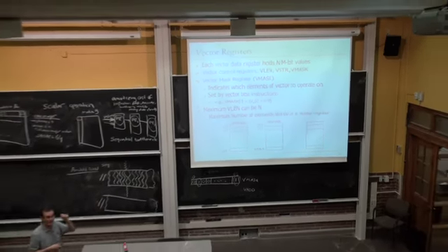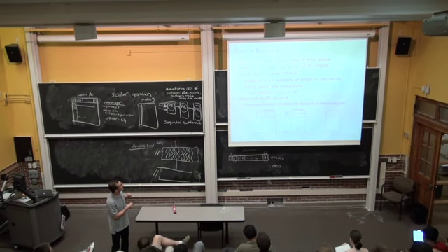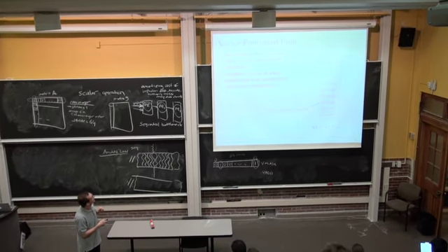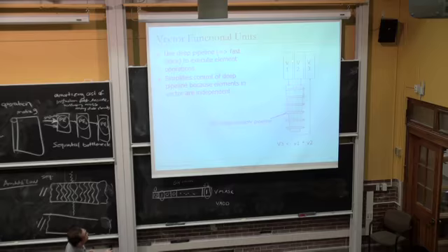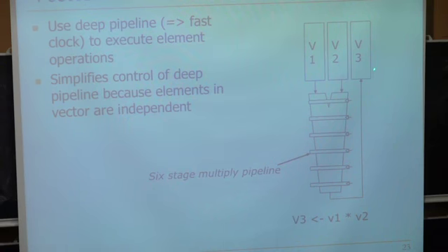So today's GPUs are actually very similar. Maximum vector length can be n. These are the maximum number of elements stored in a vector register. Okay. So if you look at a vector functional unit, it takes as input vector registers, it's pipelined, and outputs its result in vector register 3.